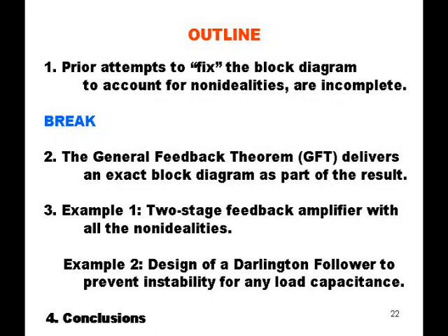And the GFT, General Feedback Theorem, is a very useful method to do that analysis, and we'll see how you can actually come up with a design criterion to avoid an instability. In fact, to do better than that, because it's not just a matter of avoiding instability, it's a matter of controlling the amount of peaking of the output response and keeping that within an acceptable limit.